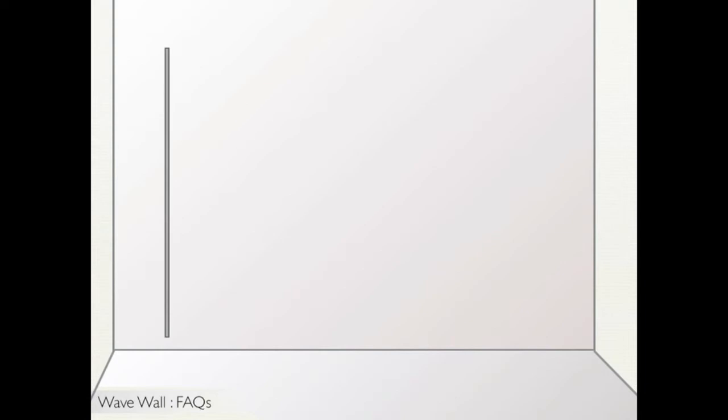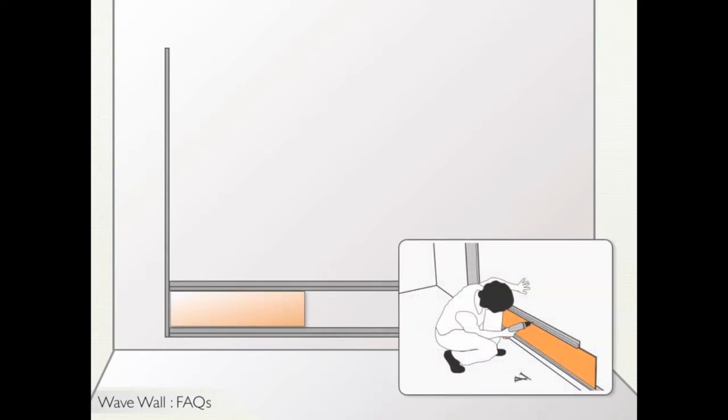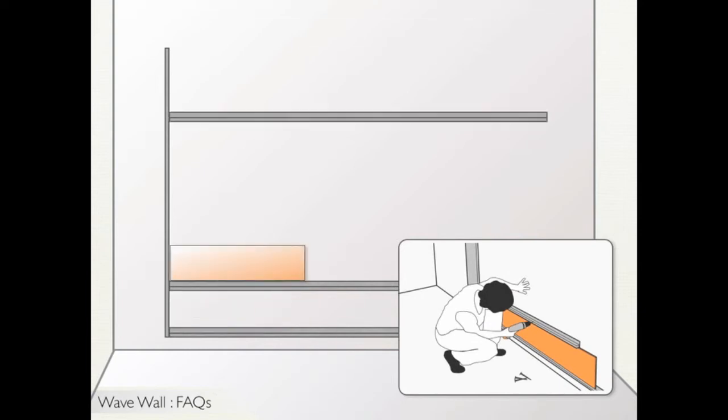First, place the first edge of the edging extrusion in the desired position and attach it to the wall with screws. Then, fit the bottom inner extrusion at the correct height and flush with the end of your edging extrusion and attach it with screws and liquid nails. At this point, the spacer can be used to correctly place the rest of the inner extrusions from bottom to top.